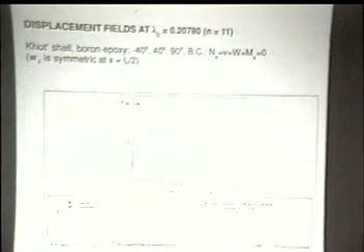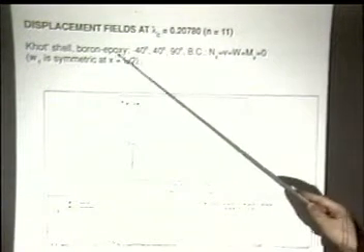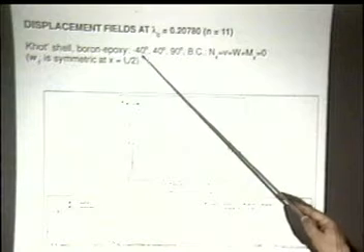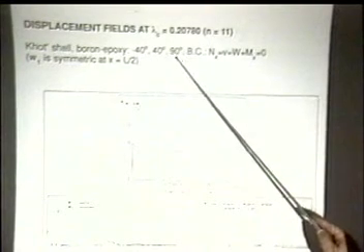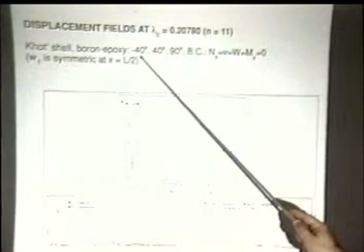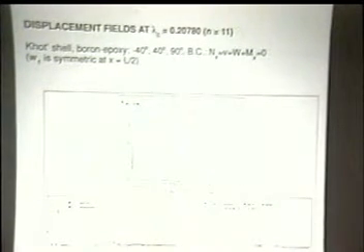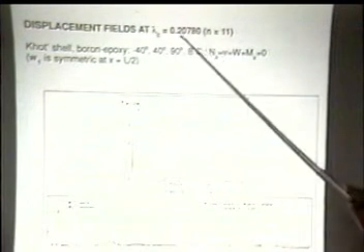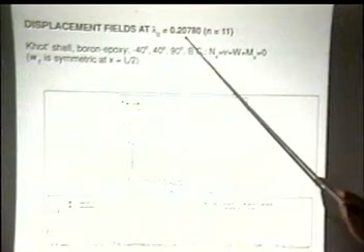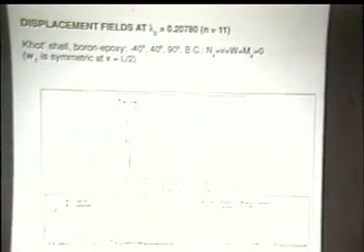I don't know precisely whether he has meanwhile retired or is still there. But anyhow, it is a shell that he has used. It consists of 3 layers. The outer layer is at minus 40 degrees, the next one at plus 40 degrees, the inner layer at 90 degrees. Boundary condition is classical simple support. And we found the first eigenvalue at 20780 with 11 waves.